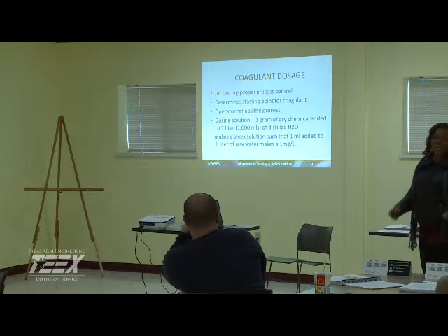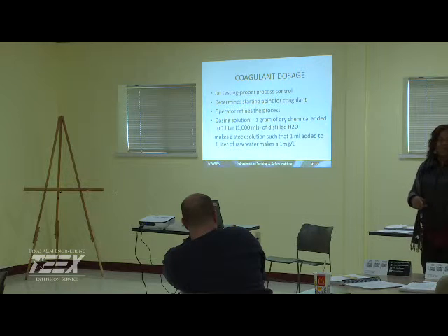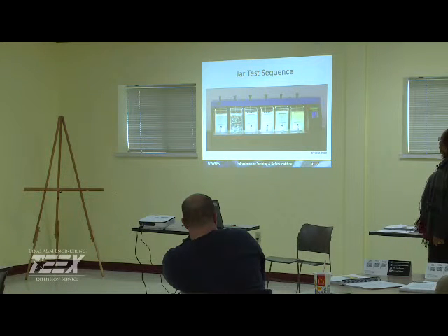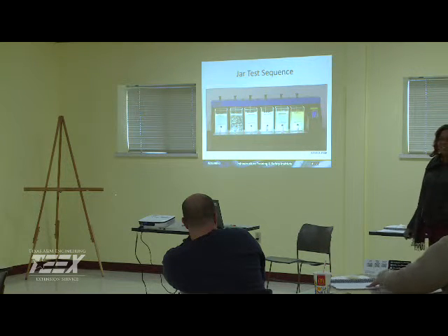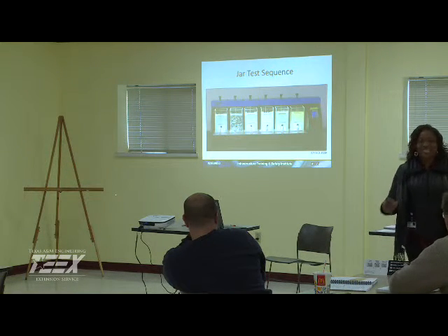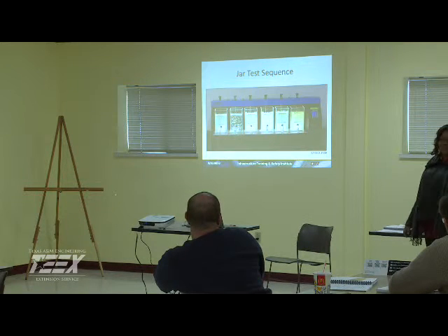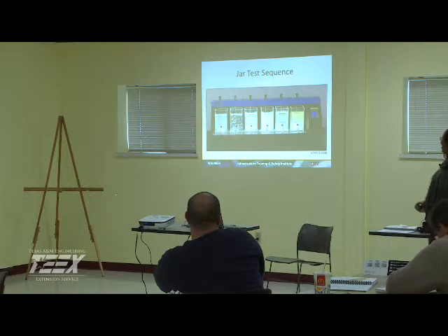Yes. Well, you don't have to go, where's my calculator, where's the formula, what's the specific gravity and all of that, what's the percent purity. So you get your right dose. And again, you're going to set up a series of jars. I was about to say or beakers or buckets, because some people will refer to them as beakers. Yeah, too. The square ones are preferred, the cubic shape or whatever. Yeah. And the round ones, I found that I won't.